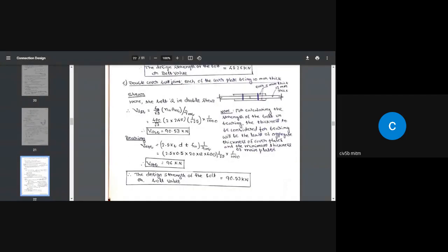here, as I said, we need to consider only 50%, any 50%. So if you apply P, the load gets transferred from one side to another through these two plates, is it not? So if you apply a pull here, this side gets pressed, okay?